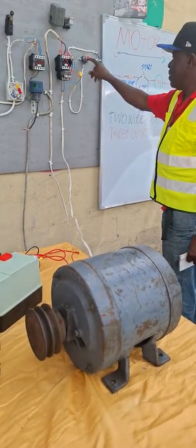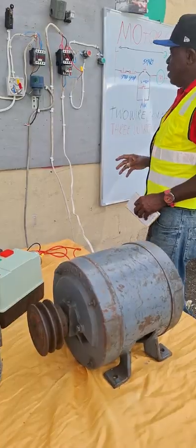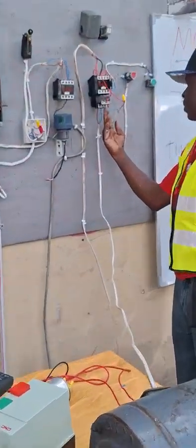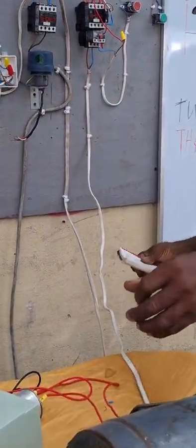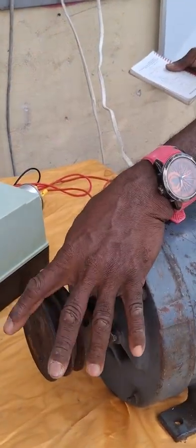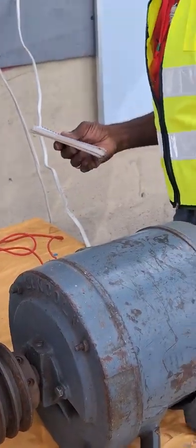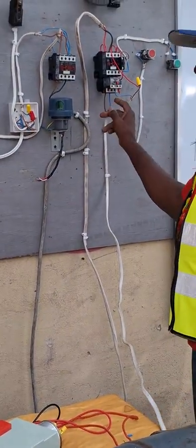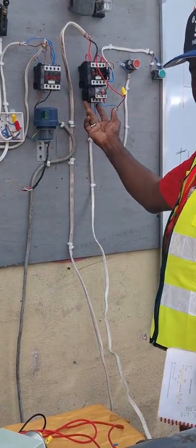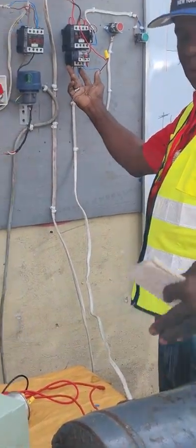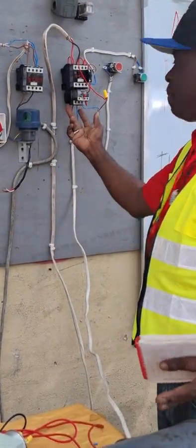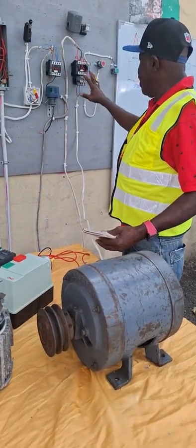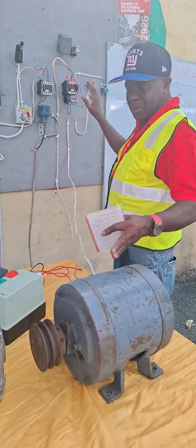Stop it, right? I remember now, and here now is the overload. So this overload in the circuit will protect the motor. If the motor jams, right, it's an overload. It's a jam or bearings from mechanical pressure, you name it. The overload here will sense the current, based on the setting, because the motor would build up heat more than it's supposed to have. It will sense it and open the control circuit, and the coil will drop out and stop the motor, right?